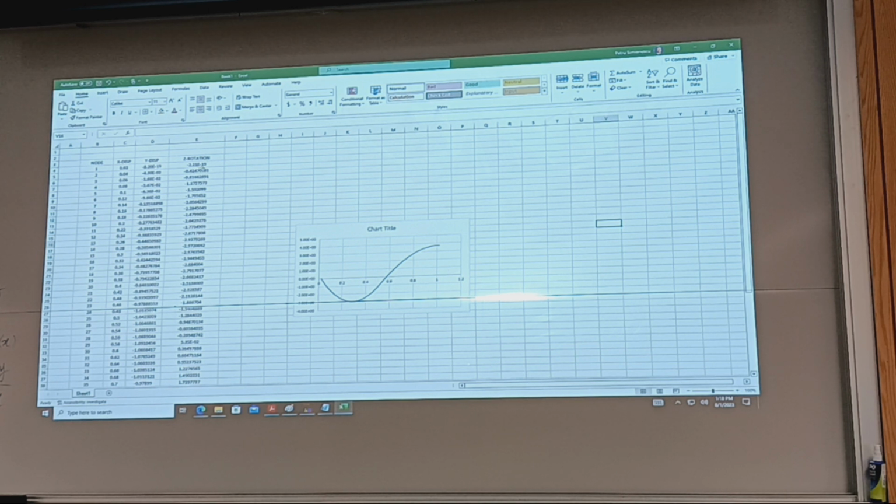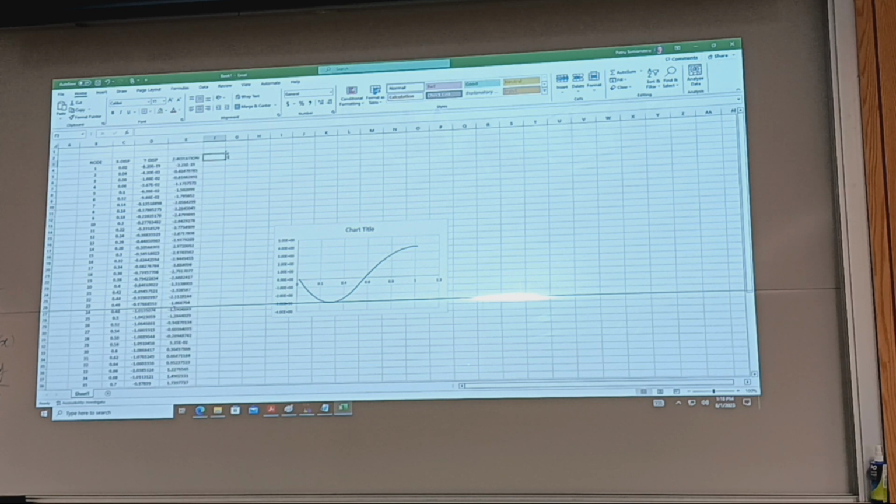And this is plot of z rotation. So the z rotation is the displacement. But this will be on camera, and you can see. So let's evaluate dy over dx, okay? Have you heard of finite differences? I'm going to apply finite differences, not calculate the slope. Let's compare with what he calls z rotation if it's indeed our slope. So theta is dy over dx. And I'm going to use, I said, finite difference. So, and that will be centered differences.